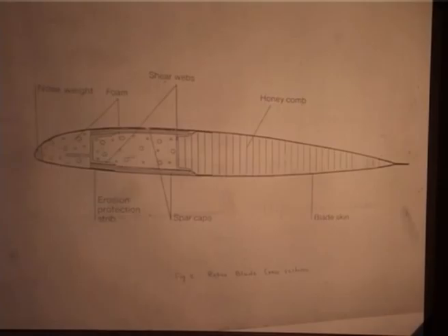I do not think in this course we will be able to learn. And then of course, your aerodynamic center is at 25%, take it as 25% because it is subsonic. Then you also make sure that the shear center is at 25%.